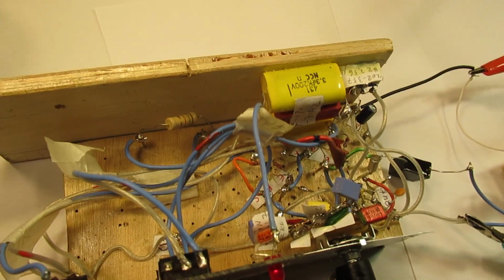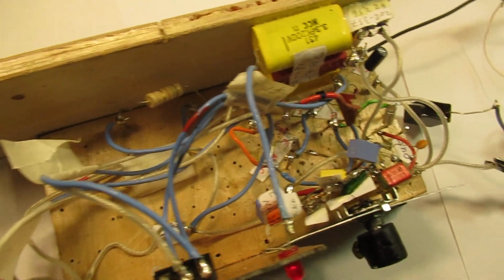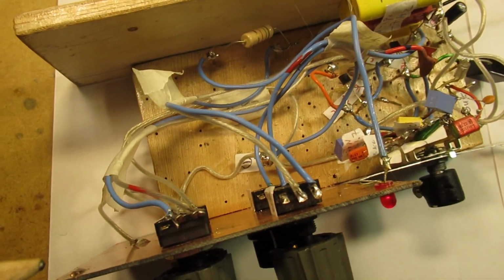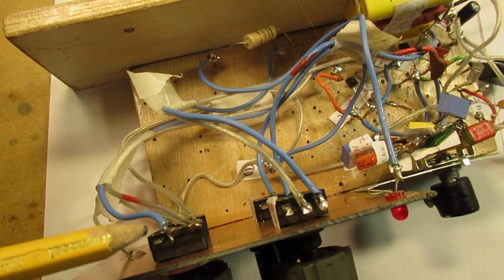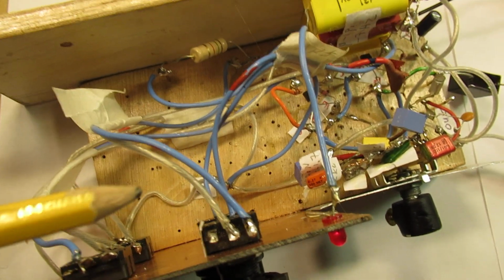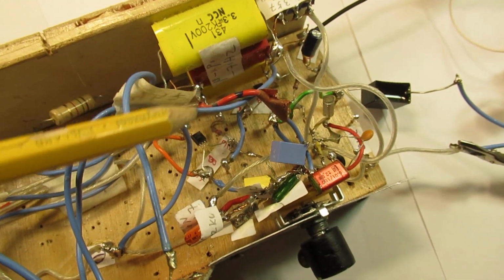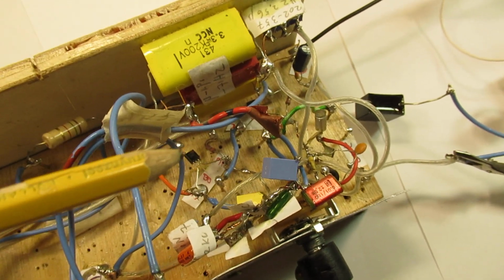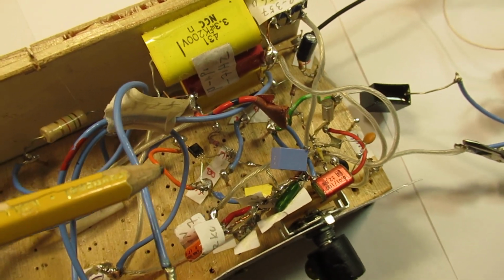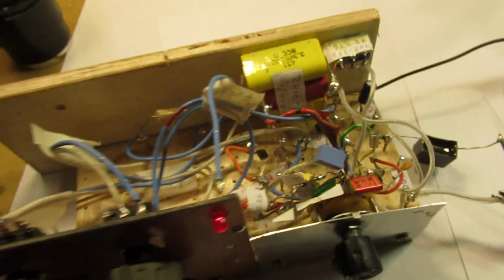Now I will give the schematic, of course, and I made it in such a way that I can now change the emitter resistance, the collector resistance, etc. And that means that with these two transistors here in that multi-vibrator circuit, you can get to all kinds of other frequencies and especially other waveforms. And that is of course interesting.